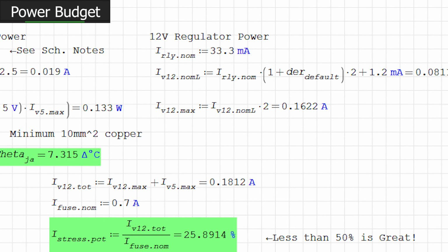It's basically a general purpose power output for future use. In this case, capable of providing up to half an amp of current at 12 volts before the PTC will have something to say about it. All told, the power supplies involved here are super happy, no issues. Let's keep moving on. We got plenty of margin in the power budget, which means that there's no further analysis or consideration required. What's next?